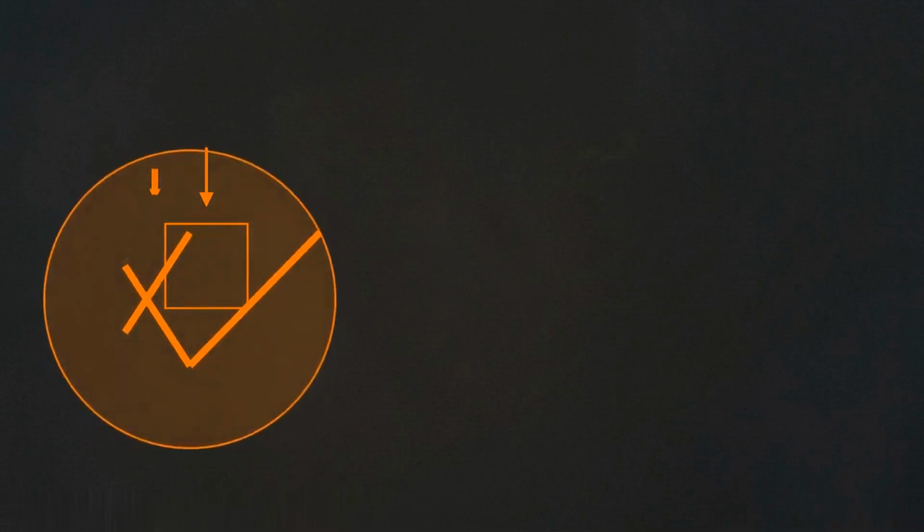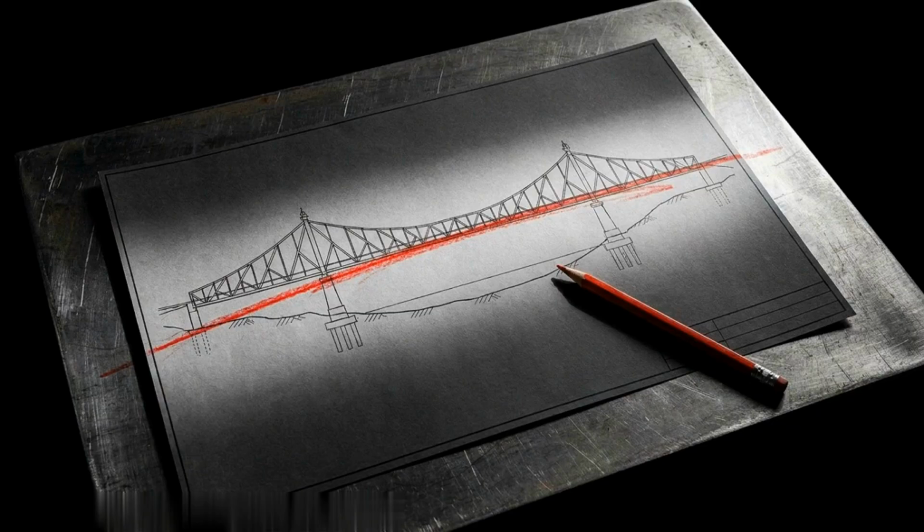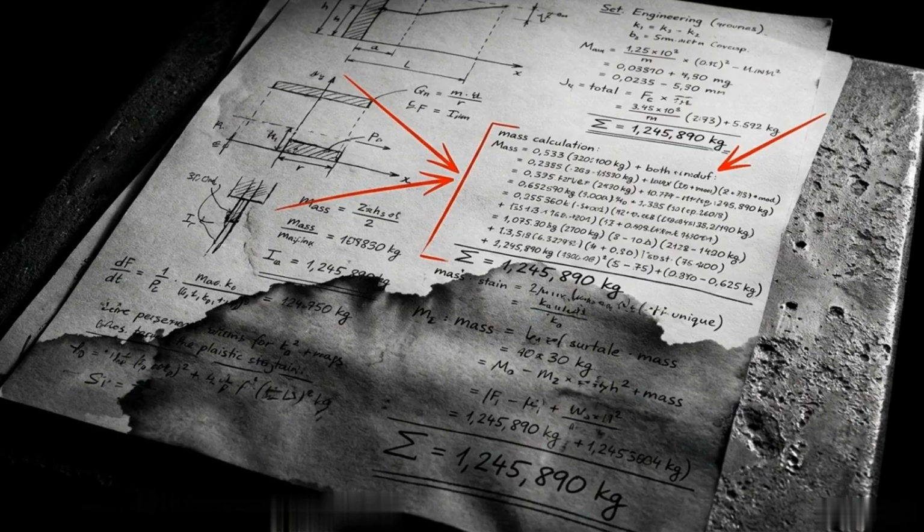Cantilever bridges face a compounding physics problem. To reach further across a river, you have to add more steel. That new steel increases the dead load, which means you must add even thicker steel at the base to hold it up. Lead engineer Theodore Cooper lengthened the main span of the bridge by 200 feet late in the design phase. However, he failed to recalculate the original dead load estimates to account for the extra mass.